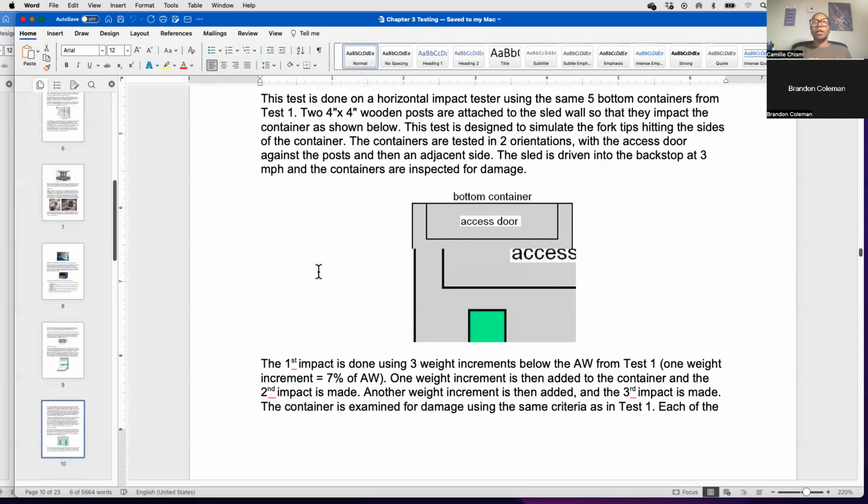You want to make sure that you don't have damage to the bin during transit, and that the bin, before it's damaged, is able to withstand impacts or compression. Let's say this gets halfway through transit and it breaks. Now this is bearing the weight, not just of what's in this bin, but also whatever's on top of it.